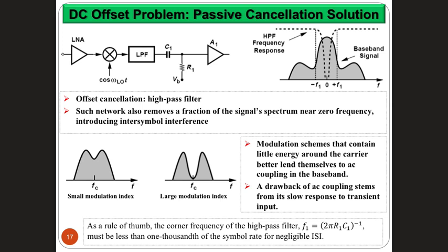We call that inter-symbol interference because the symbol can no longer maintain its shape as a square. It spreads a little because of that filtering effect, and then it has a significant value affecting the next one. You know what inter-symbol interference is, right? You have a symbol, here is a 1, and the next one, let's say, is 0.